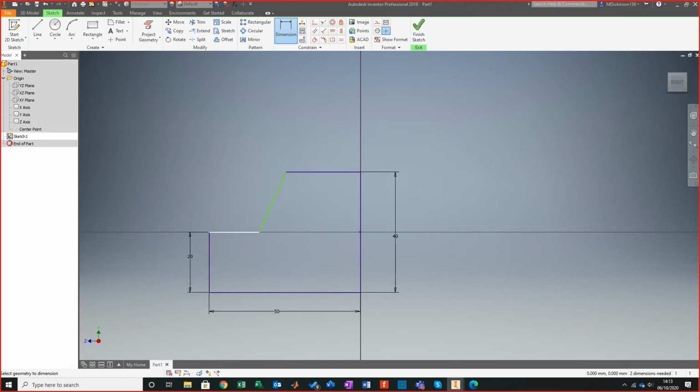Then my distance between this point and the back plate is 12.5. And we have an angle there. So what I'm going to do, just to help me, I'm just going to drag that across. It just makes my life easier, because I'll go that point to that back plate, and that's where my angle is going to come from. So this angle, according to this drawing, is 9.5.